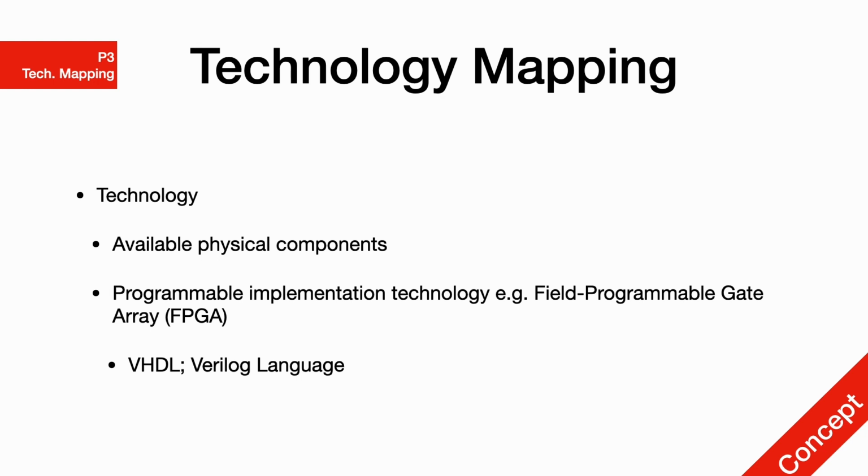Aside from all this, it is also important to know some of the common things that could happen inside technology mapping. The basic physical gates that we encounter a lot now, for example, AND gates, OR gates, and NOT gates. It is of vital importance that you understand alternatives to implementing these gates when they're not physically available. In some of the previous examples, we've already taken a look at implementing a NOT gate without using an actual NOT gate, but by using a NAND gate, an AND gate with an inverter. So, let's take a look at some more examples of that.